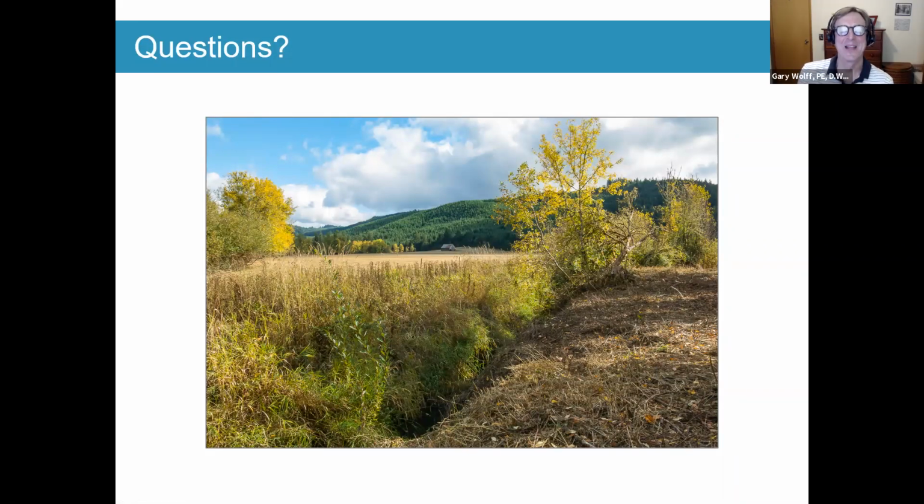Okay, well, that's a really good question, and it's a big challenge that we often run into in these hydraulic design projects. See, the hydraulic engineers are predicting scour basically in most cases assuming that the material is erodible. Now there are some of the scour equations, particularly in the later versions of the Federal Highway guidelines, that will account for things like a large material, like coarser bed material in the scour calculations that will tend to limit